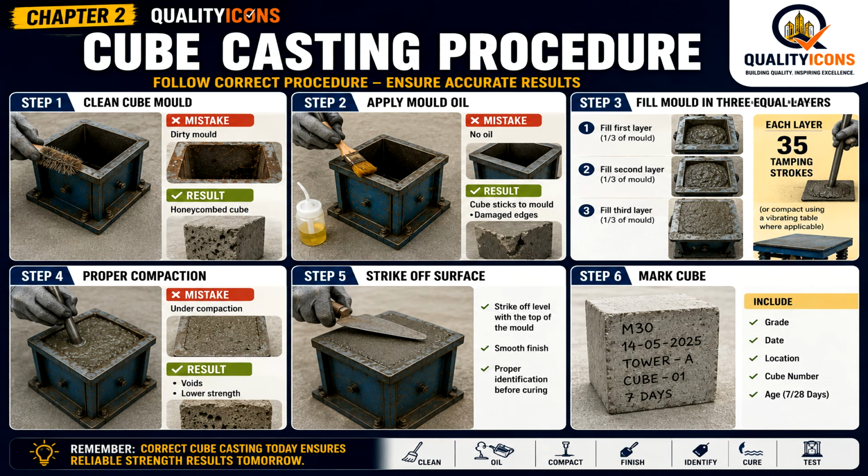Step 5. Strike off the surface. Strike off level with the top of the mold. Smooth finish, proper identification before curing.